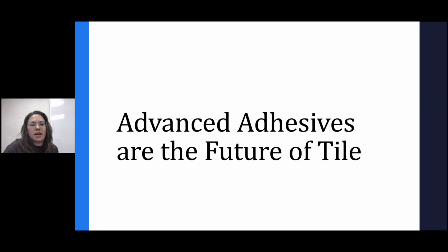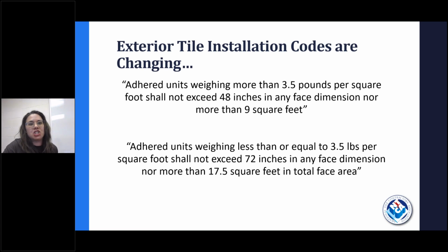So let's talk about these advanced adhesives, and in my opinion, I think this is where a lot of the tile world is going, and it's because of things like changing code. Okay, this was taken directly from the 2021 IBC 1404.10.2, which says that traditionally, you needed to anchor in any exterior tile because traditionally exterior tile were very, very heavy, right?